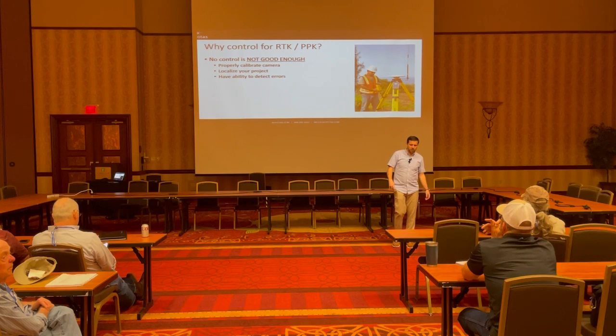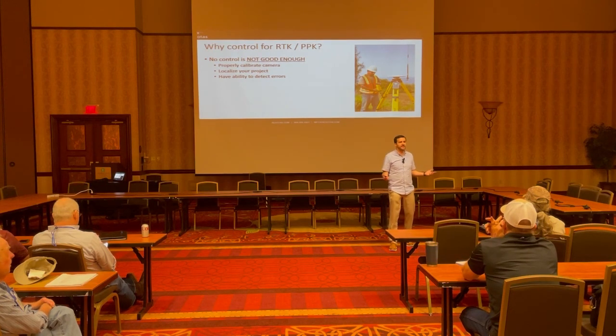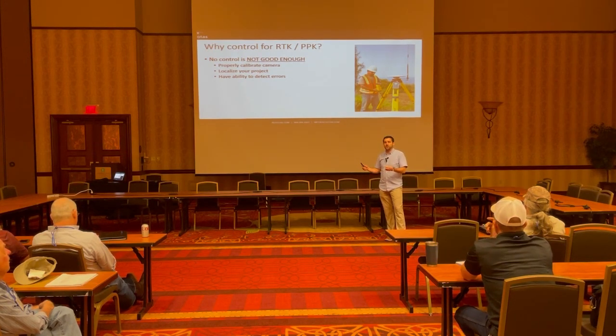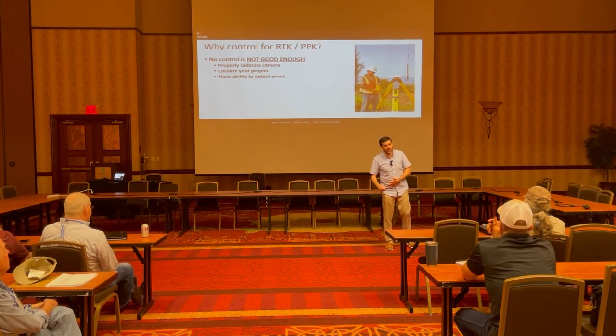This is another thing that's bigger for me coming from California. It's seismically active there. The ground moves by a couple of tenths of a foot every single year. So if you want to actually have it match up with other boundary or prior surveys, you have to localize it to a job site.